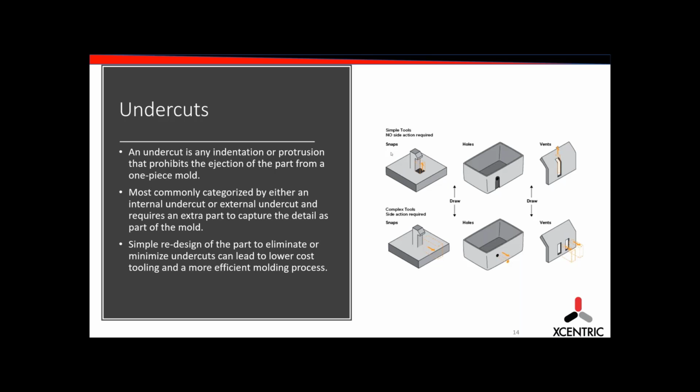Okay, so a similar question from the same person is, how about materials? How do they affect the injection pressure? It's going to come down to what the viscosity of the material is, right? What kind of fillers do we have in them? What is affecting that material from flowing? If it's a standard, higher viscosity material, it's going to be different than a really low viscosity, heavily filled material. So it comes down to what your material selection is for your part and your geometry, and then even goes back and builds on your runner type, right? So that's going to affect what kind of runner you need, so we can get that plastic through the gate into the part filled and packed.